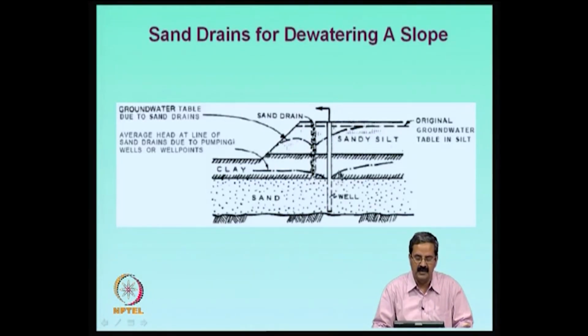So what he did was make a hole like this, put in geosynthetic drains, prefabricated vertical drains, and connect them to the sandy layer that existed below. With proper spacing, he was able to connect the whole waterlogged area to that sandy layer, and within 1 or 2 days the whole area totally drained off.